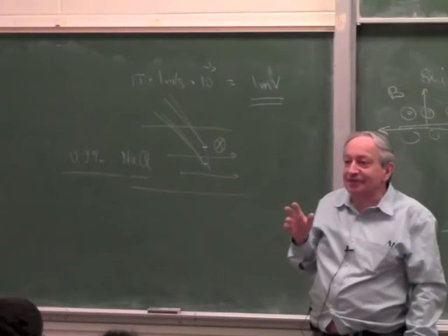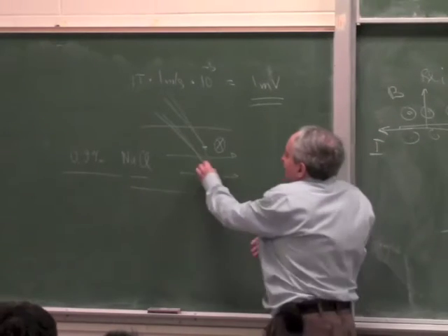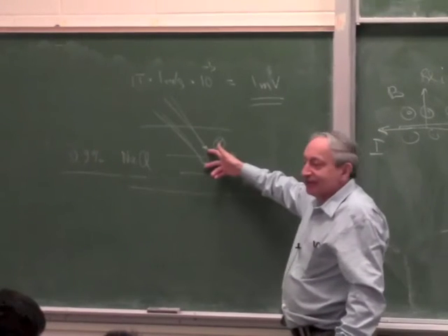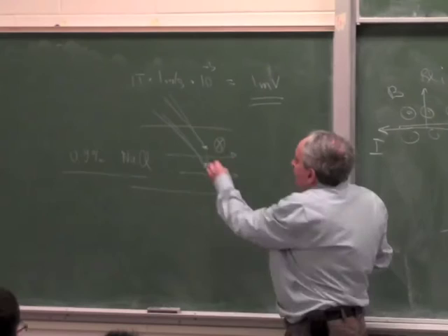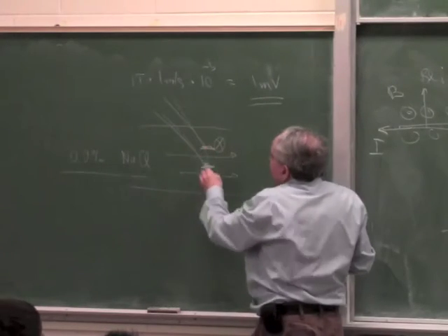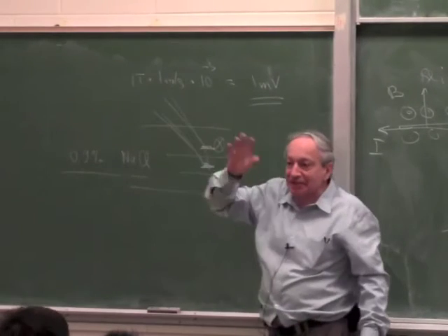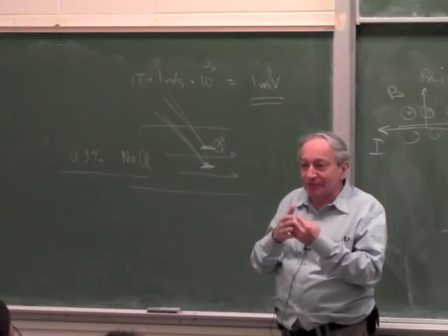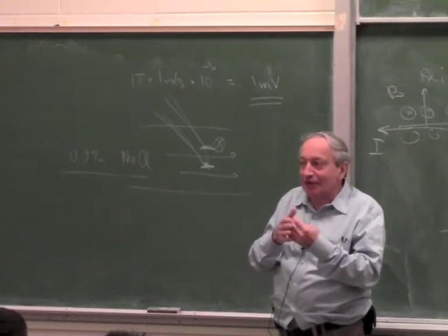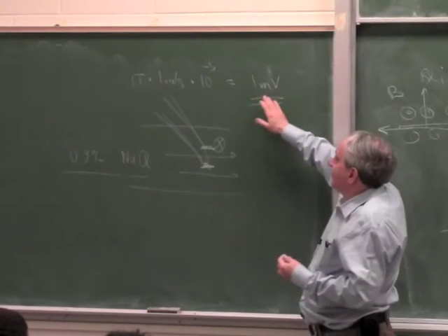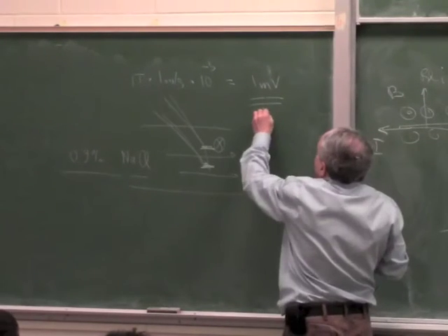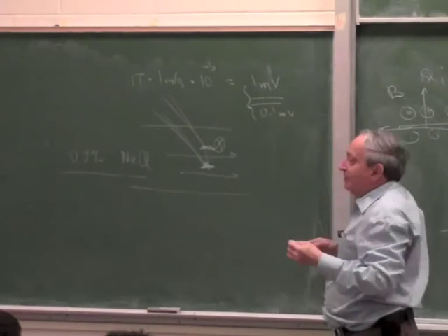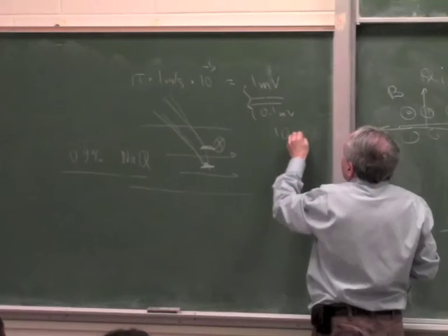Now, of course, there are problems. When you do that, there is also some galvanic effect, because this also forms a battery. Let's say you have 2 wires and the metals are slightly dissimilar and the needle is the third metal, so you also get DC voltages because it forms batteries. So if you want to measure this 1 millivolt or 0.1 millivolt to 1% accuracy, you have to go down to 10 microvolt.